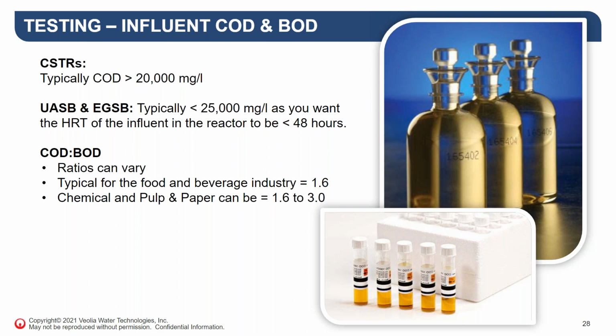Where'd that 48 hours come from? To be honest with you, I don't know. We just know from experience that if the HRT is greater than 48 hours, you're not going to get granulation. And if you don't get granulation in the UASB and EGSB reactors, that bacteria is not going to stay in there. And if you don't have bacteria in your reactor, it's not going to work.